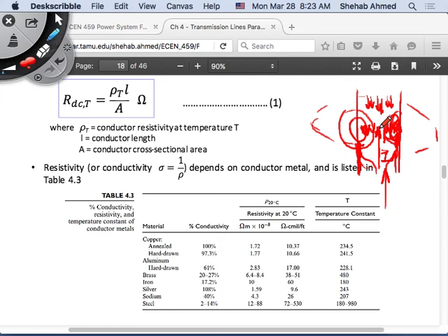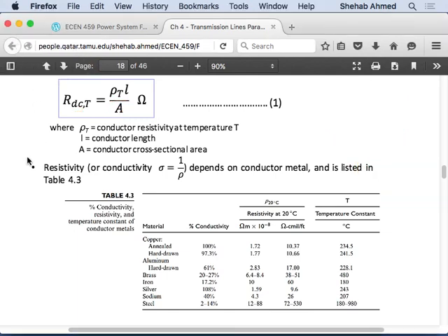When you push it to the outside, this current is flowing in a smaller cross-section area, right? We said that if current is flowing in a smaller cross-section area, the resistance will do what? They're inversely proportional. The resistance and cross-section area are inversely proportional here, which means the resistance will increase due to skin effect, right? So you're pushing the current to move only on the outside of the conductor, causing an increase in the resistance. We have a table in Appendix A3, I think.